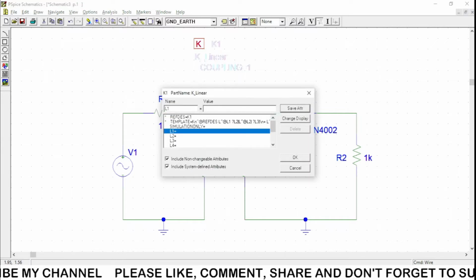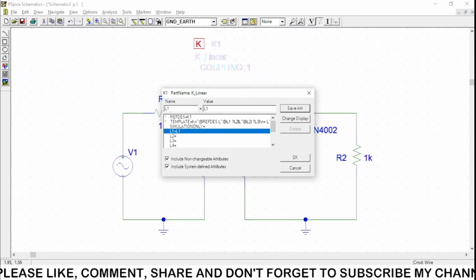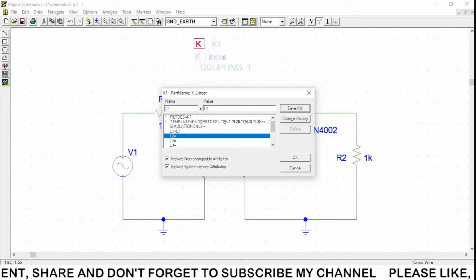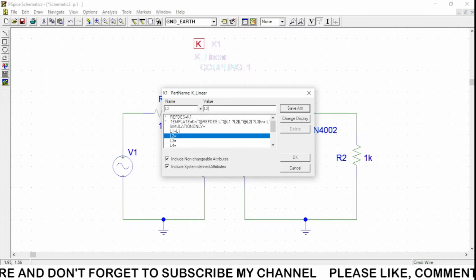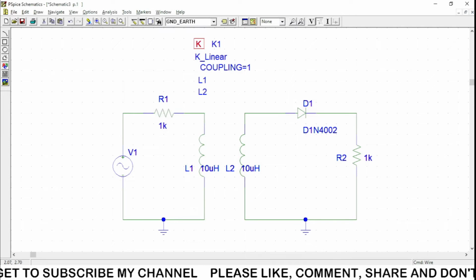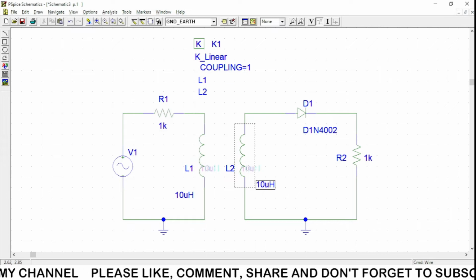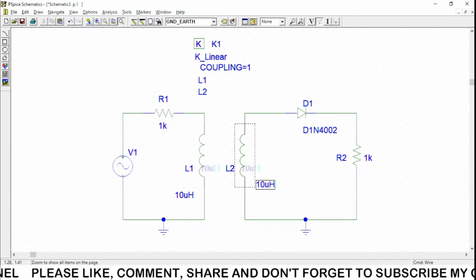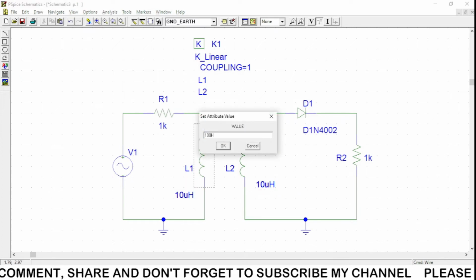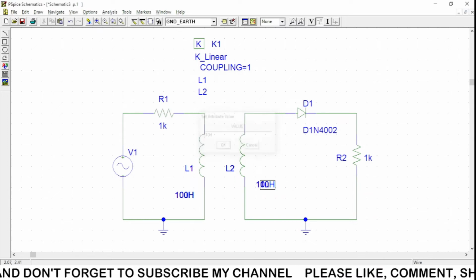We have to name the L1 as L1 actually. Save attribute. I recommend seeing this in HD so that you will be able to see the smaller font size of what I am typing. So L2, saying OK. So this is done. This is a transformer now because the inductors are connected like a mutual inductance concept. Okay, so what we need is to make it step down. So I am taking it to be 100 Henry and taking it to be 10.